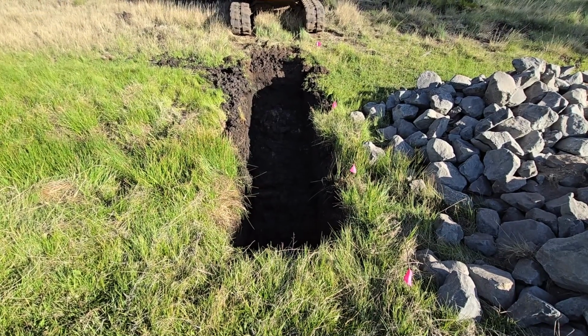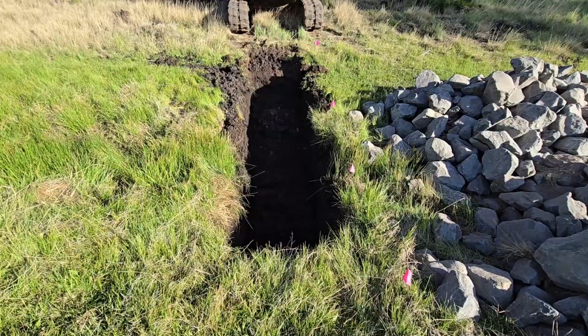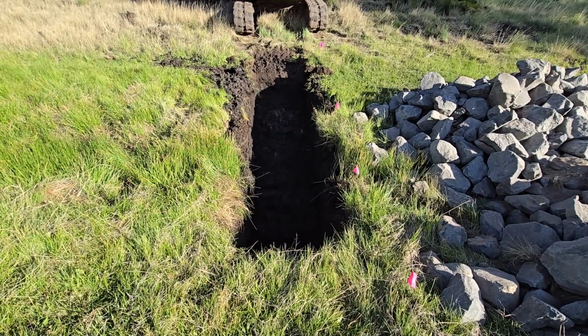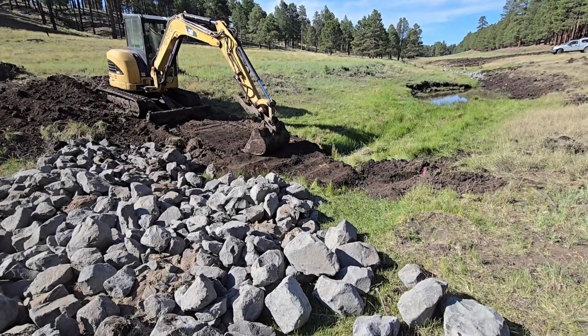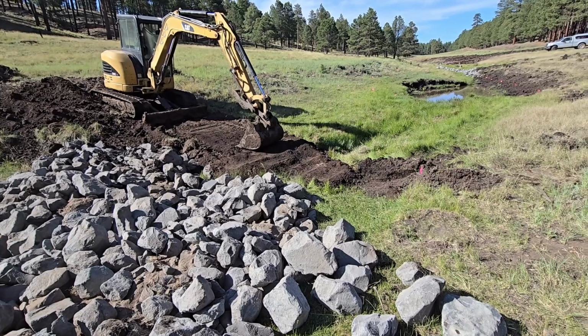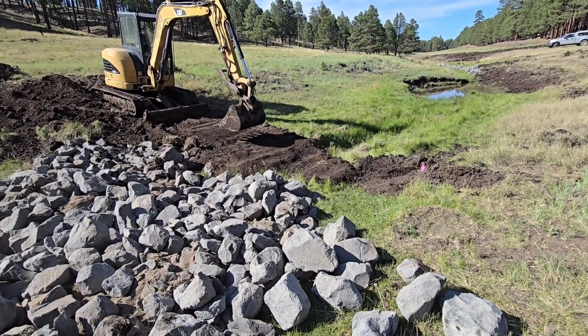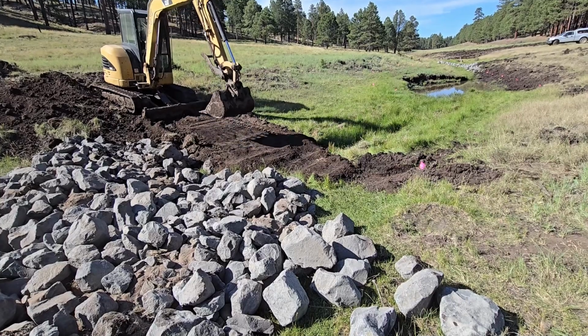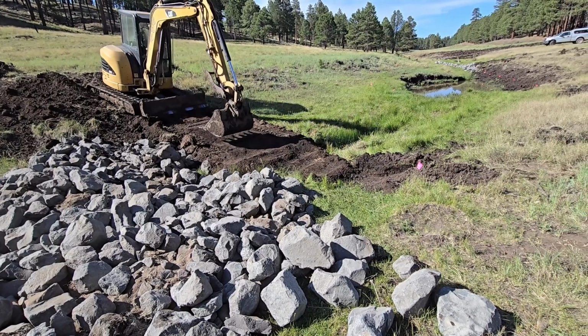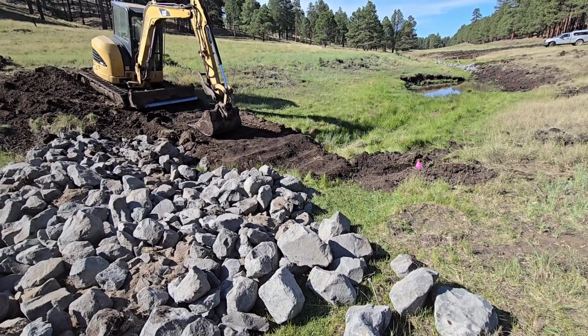If you take shortcuts in building the groundwater dam this narrow, it won't do what you want it to do. Don continues to use the excavator to fill the core trench with layers of clay, using care to compact each layer of clay so it will hold water and not leak. Digging the core trench goes fast, while filling it takes a long time.